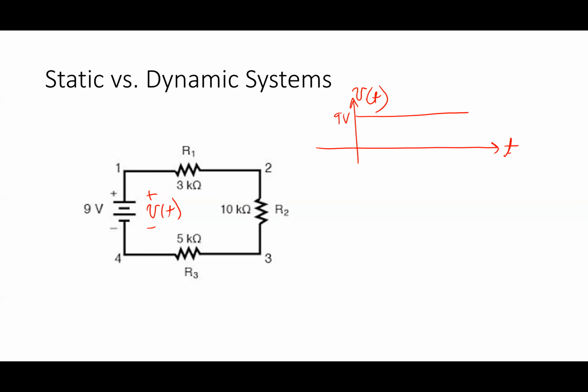Which with a 9-volt battery, turning the voltage source on, if I want to model that, you're basically mathematically modeling sticking the red wire into the breadboard. Okay. So what's I of T, the current in this circuit, look like? What would that look like? You don't need to worry about giving me a number. I don't care about the number, right? The number is tricky to calculate. It would be 9 divided by what? 18K. All right, what would it look like though?